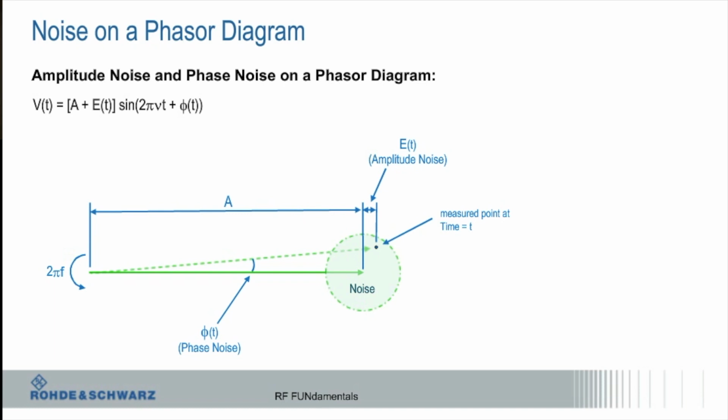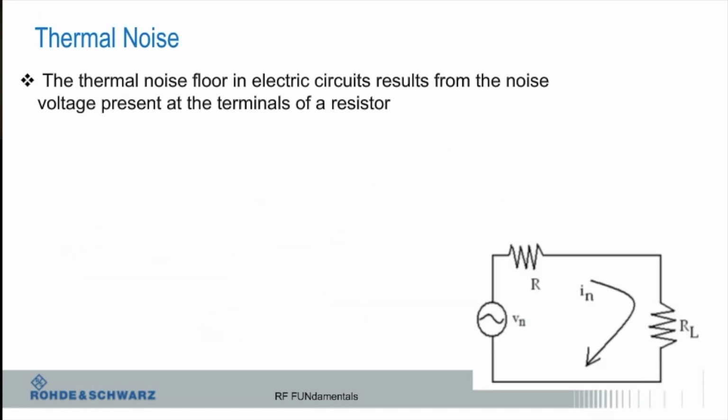Yeah. Okay, thermal noise. Obviously, thermal noise is just there, and you have to deal with it. It's sort of modeled by the terminals of a resistor. That's the minus 174 dBm per hertz. It's distributed evenly. So when you look at noise, like we had phase noise where we have a carrier and it's sort of spread out a little bit, that's one type of noise.